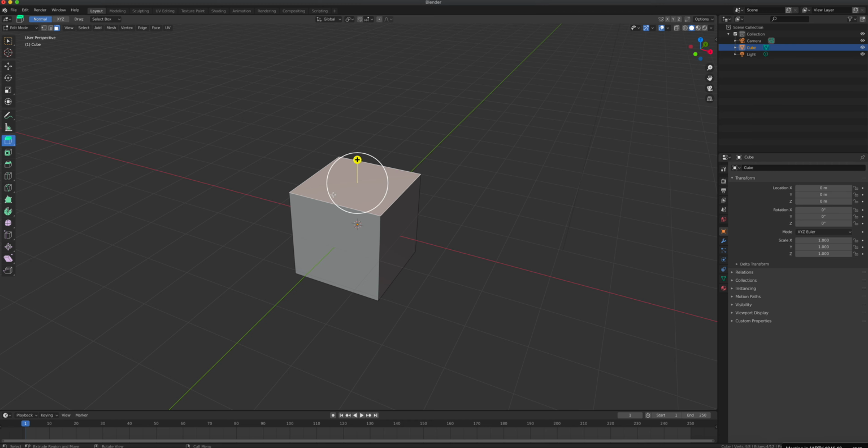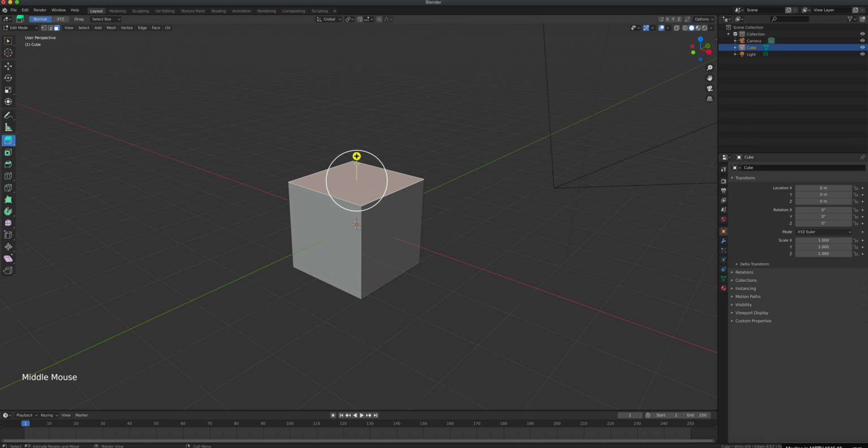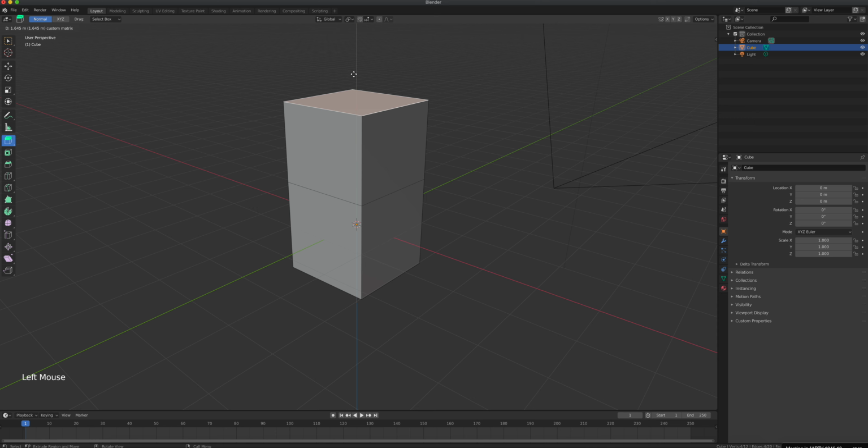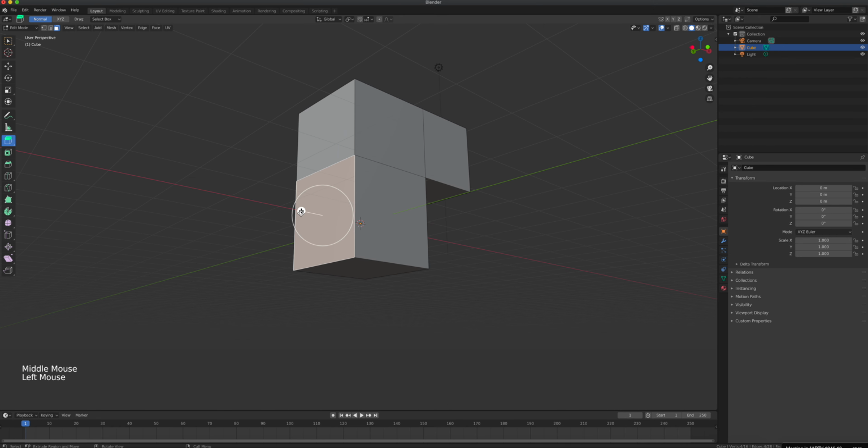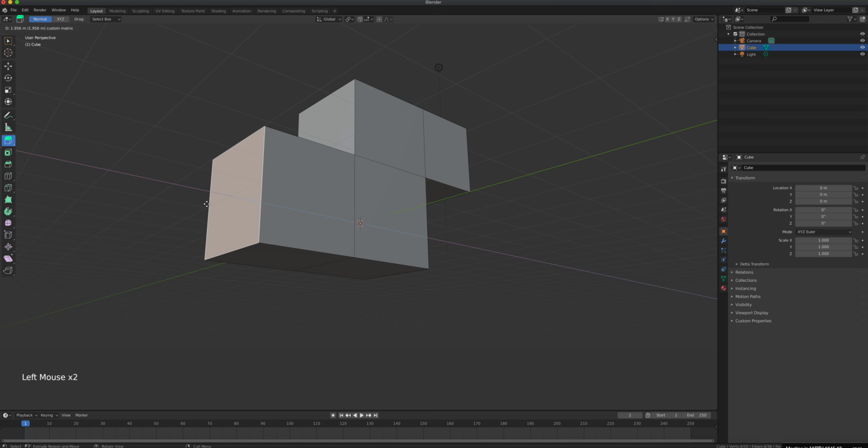However, you have this yellow handle with a little plus. Okay, so if I drag that one up, that would be the same thing as pressing E and moving my mouse. At this point, I recommend you do this type of extrusion because it's more interactive and very visual, right? When you're just starting, this is important. So if I select that one, I go like here. If I select that, I can extrude there.